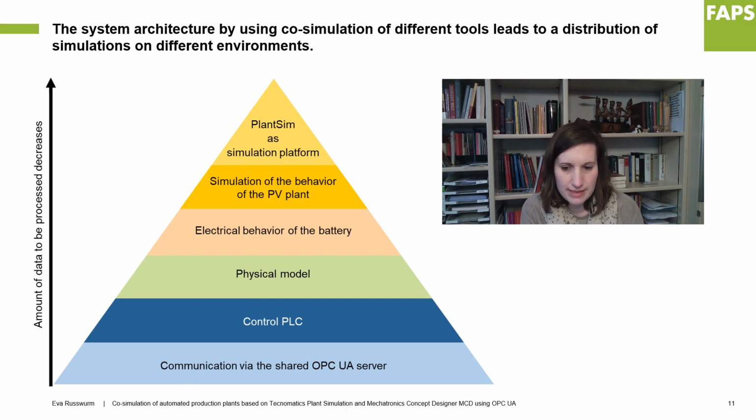In our present case, the OPC UA server has the greatest data load because the server must process, store or buffer all data. The controller, which controls both process and energy management, also has a high computing share. This could be changed to a distributed control periphery if wanted and if needed, so you have to use more than one PLC.